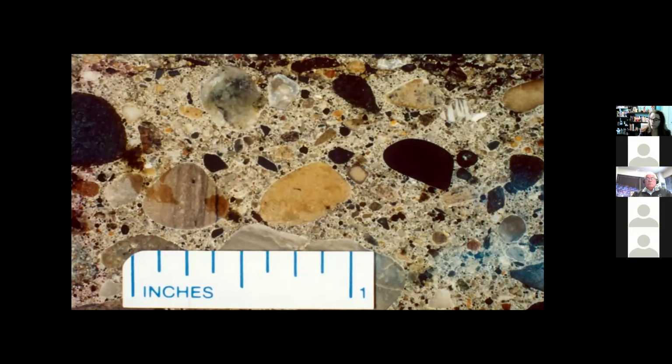So one way we do that on vertical structures that have delaminations is we use bush hammers, but we like to use lower impact, because if you're just going to remove it with a hammer, you're probably bruising the surface. So then to put an overlay on it isn't necessarily going to bond to anything that you've beat the heck out of. So same concept with a surface slab. If you're going to do that, then you need to be able to remove it safely and keep the good quality concrete intact.